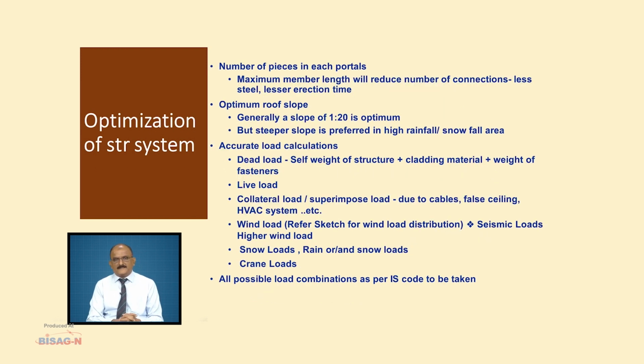Then number of pieces in each portal. This depends upon what is the maximum size of the portal piece or portal beam or the column which we can carry to the site. It depends upon so many factors, like the geography of the place or the road infrastructure available, vehicles available, size of the structure, amount of steel used in the structure, and capacity of the manufacturer also.